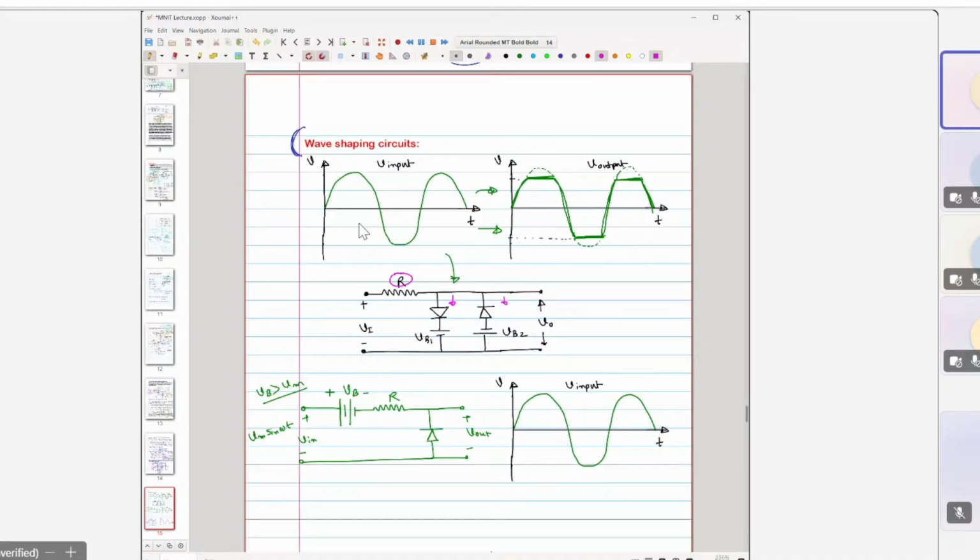So you need to limit the current, and you have to make sure that you are choosing this R value correctly. Another important point is that this R value should not be too large, because if this R is too large, then the current flowing through it will produce a significant drop across this R only, and it would be very difficult to make this circuit operational. So you have to choose this value of R carefully.